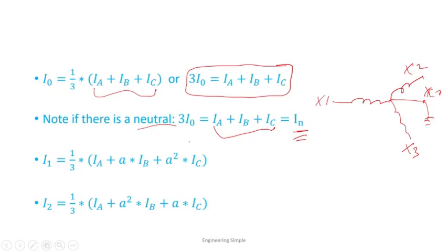So anytime you have a grounded Y transformer, this neutral here will see 3 times the zero sequence current. If there is unbalance due to single phase loading or a line to ground fault, basically anytime you have either unbalance like single phase loading or a ground fault, that's the current that would flow through the neutral. So that's important to remember.